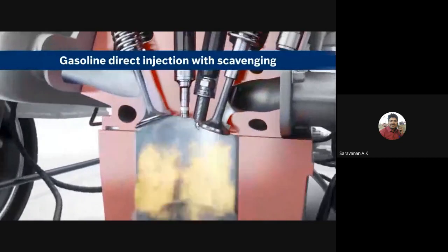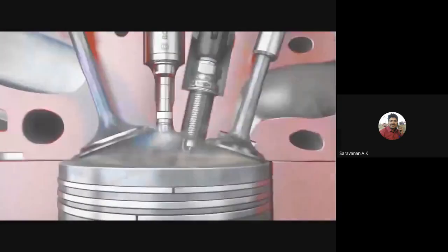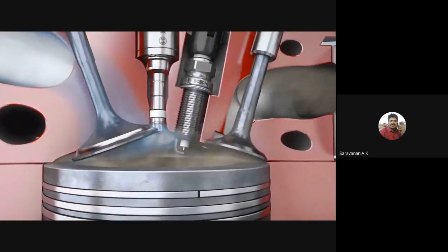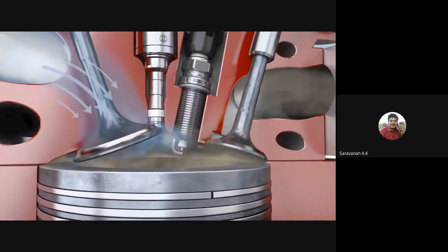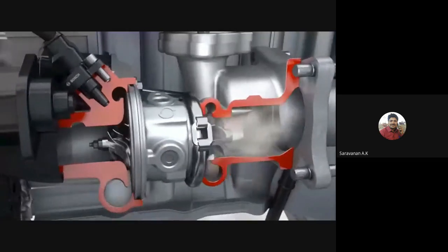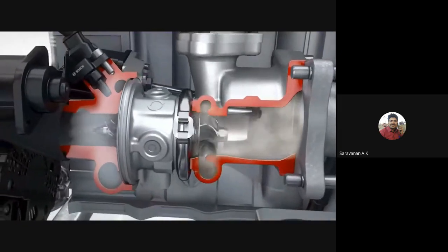To this end, the intake and exhaust valves are open simultaneously for a moment. This creates a dynamic pressure differential between the intake and exhaust sides of the engine. Fresh air flows in and out through an exhaust valve towards the exhaust manifold. The increased flow of exhaust gas creates 50% more torque at low engine speeds, counteracting turbo lag.